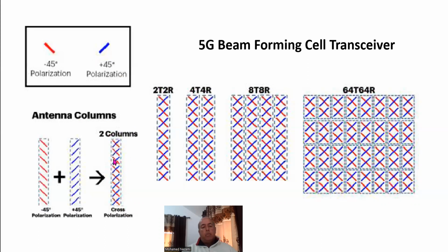Because it has vertical and horizontal polarizations, this is really 2 transmitters and 2 receivers, since we're sharing the antenna for both the receiver and the transmitter. It's a time duplexing system, so this antenna is hooked up to 2 transmitters, one for plus 45 degrees and one for minus 45 degrees. Now you could transmit either; this is for the system designer or the system deployer to decide.